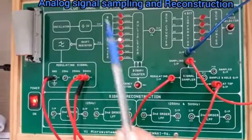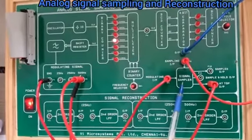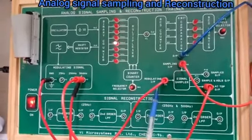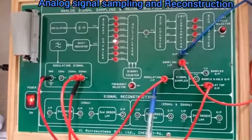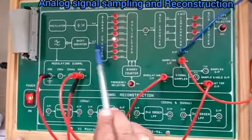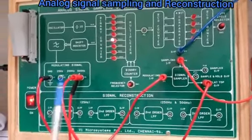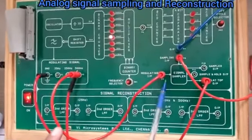For the sampling process, we have the signal sampler. In this trainer kit we have a signal sampler. It is a switch, and it needs two signals. One is the input signal, that is the modulating signal, the signal which is going to be sampled by the sampling pulse. That is the analog signal. Here we have different frequencies: 225 hertz, 250 hertz, and 500 hertz. Among these three frequencies, you can select any one at a time, and that frequency is applied at the input of the signal sampler.